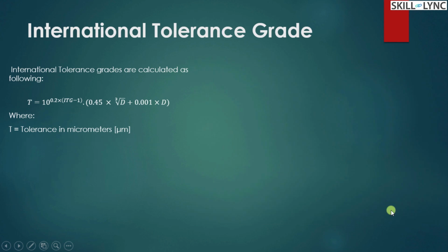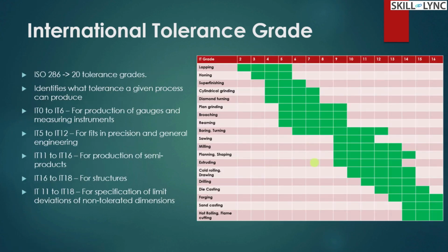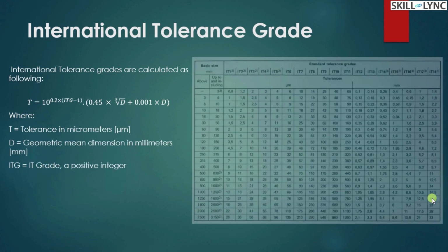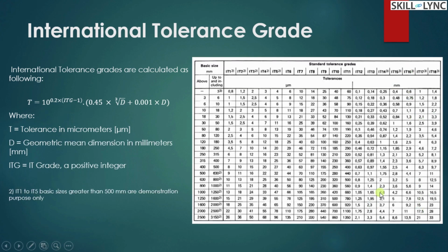So let us go back to this previous slide to see typically how the object is manufactured. Initially the tolerance is controlled at the first level by the first manufacturing operation, for example a forged component. If you go for a piston rod, you go for forging, wherein you initially control the tolerances, that is, from a band 13 to 16, which lies in a maximum of 30 mm, minimum 3 mm. So in this zone you specify the allowed condition for that operation.